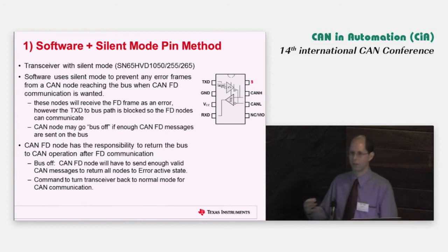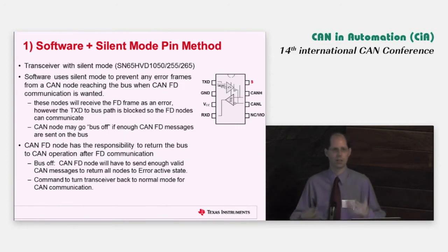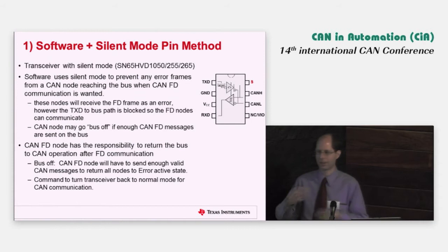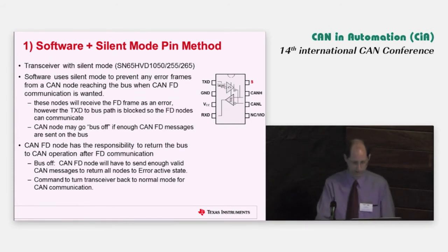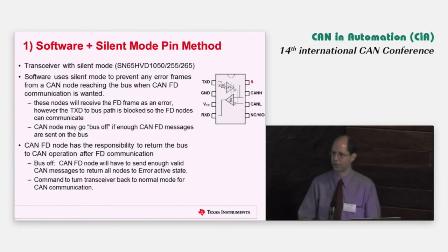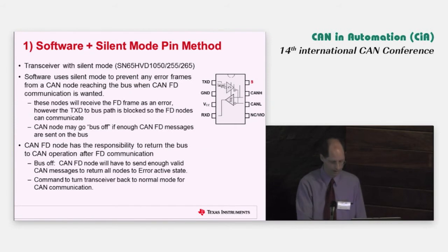So if you don't have enough FD traffic to make up for the time lost when you're switching the buses around, this may or may not be of benefit. But it's obviously a simple and a fairly low-cost way to introduce a mixing of CAN and CAN FD today.